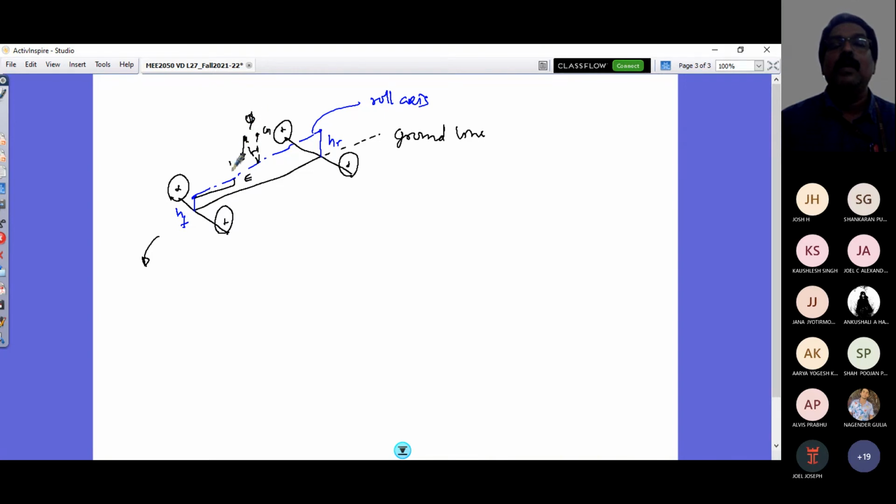And that would have my W, and my centrifugal force, which is M V squared by R, or W by g in terms of W. So this is my centrifugal force for the equilibrium. Right. So now what is this height? This height here is H1, the distance from RC to the CG location is H1. Right. So this is my model now.